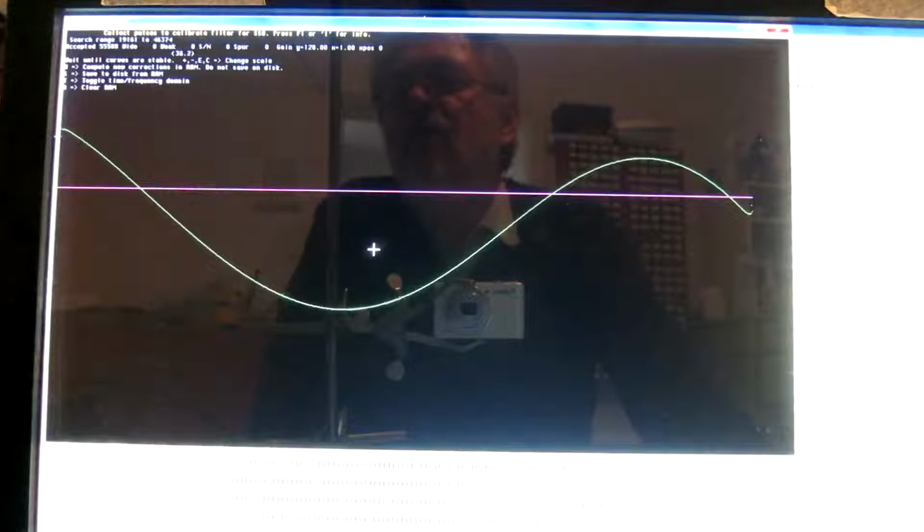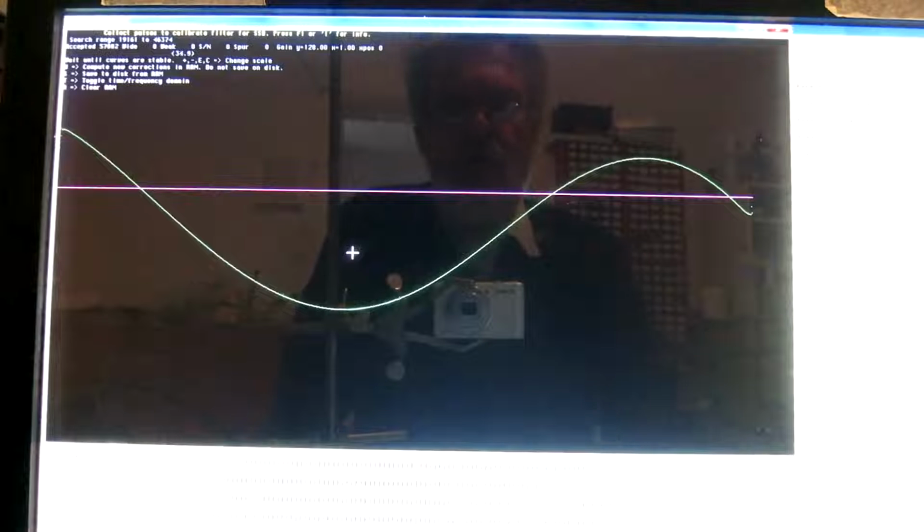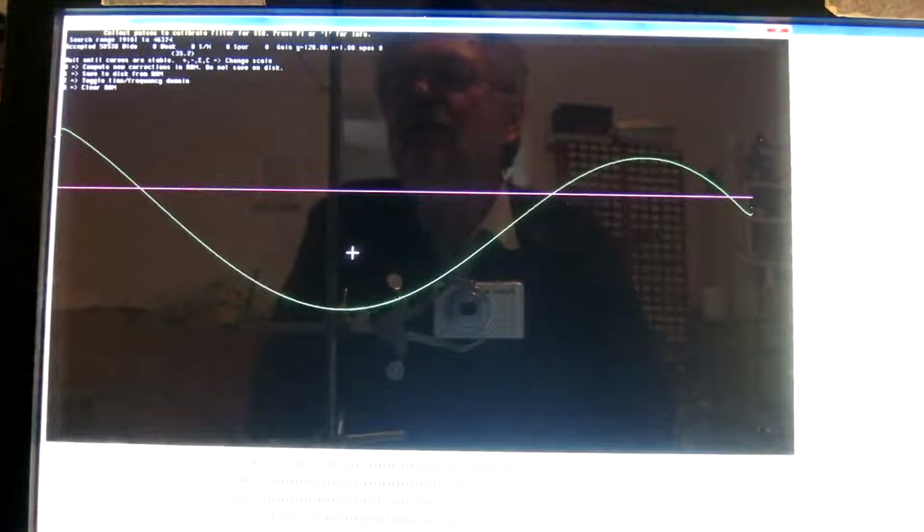Now I have 50,000 pulses. I've been talking too long, but there's no harm in that. You compute a new filter. And this is the default that Linrad suggests. You can see that there will be a little bit more gain at the band edges, and that's because the gain in the SDR-IP is lower here and here, and for that reason Linrad has to apply a higher gain.